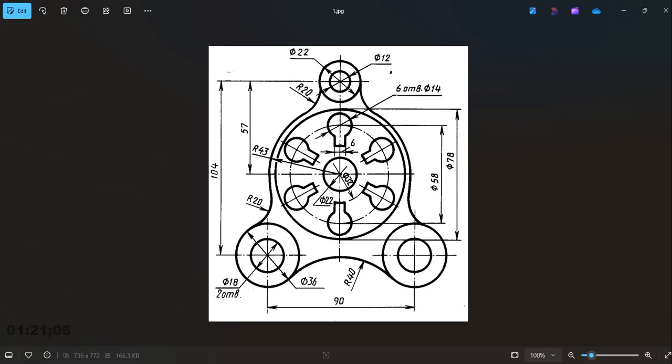In order to make this drawing effective, it's good to start with our center lines. Now I can see a vertical center line and a horizontal center line, which is the main center line. After which I will move to other center lines in the drawing. To accomplish the center lines, I'll be making use of a tool called the construction line in AutoCAD.